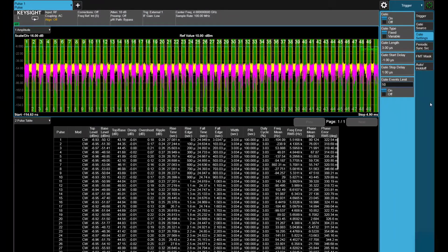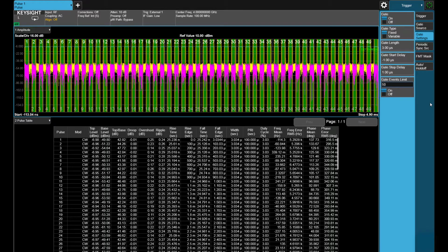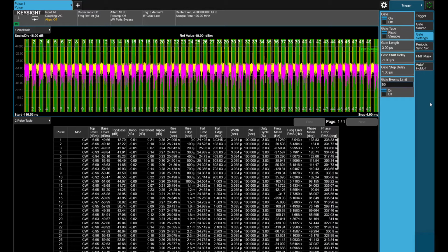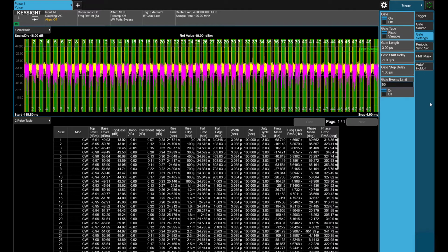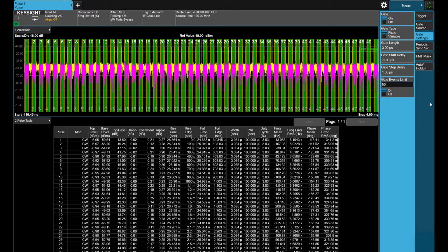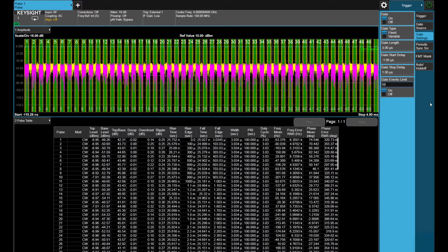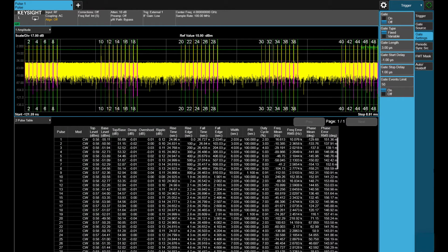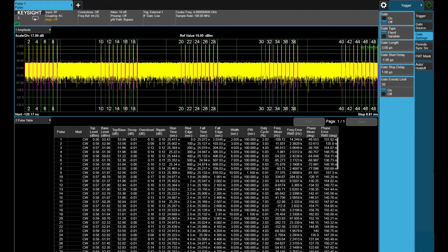If you recall, we could capture up to 50 milliseconds worth of time. If we're only capturing 5 microsecond segments, that means now we can capture up to over 15,000 pulses. Now that you understand how gated acquisition works, let's switch gears to a more complex signal. Take a look now at this bursted pulse signal.